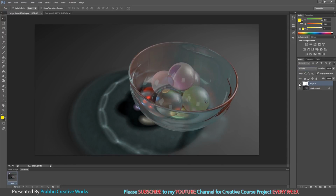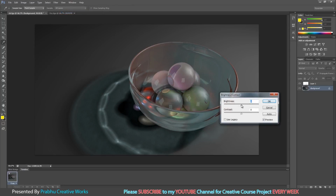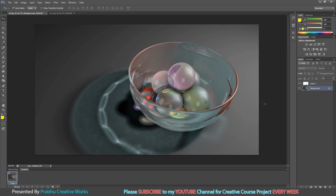So that means, see here, we don't have any shadow without occlusion. When I turn on occlusion, you have some contact shadow over your objects. Now I want to increase the brightness a little bit for our object. So I will select my background layer, go to image adjustment and choose brightness contrast. Increase a little bit of brightness and decrease a little bit of contrast, like this, and press OK. Now we have comped our images.